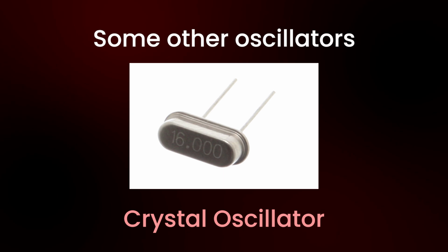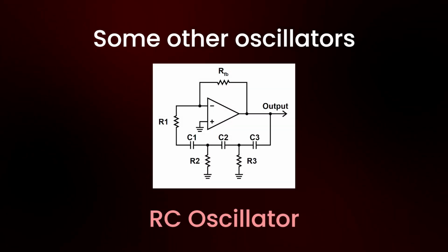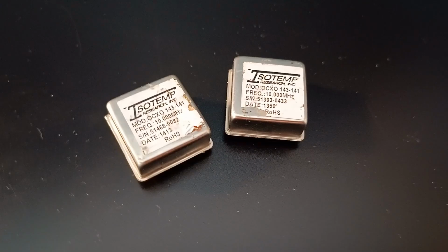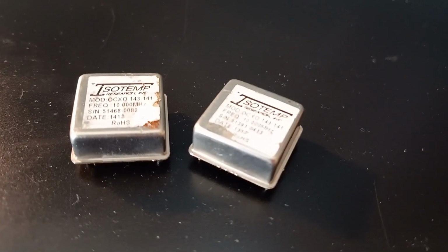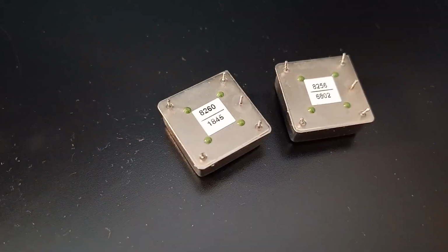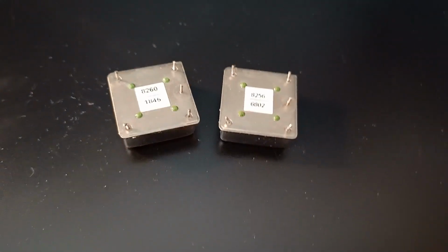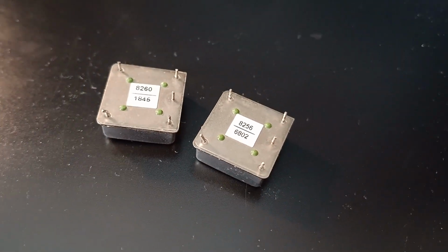First of all, we have the OCXO. As I've previously said, an OCXO is an oscillator. There are lots of kinds of oscillators, for example, crystals, MEMS, RCs, TCXOs. An OCXO is an oscillator which heats up to a certain temperature, which guarantees that external ambient factors will not affect it. And so it generates a very stable clock signal.